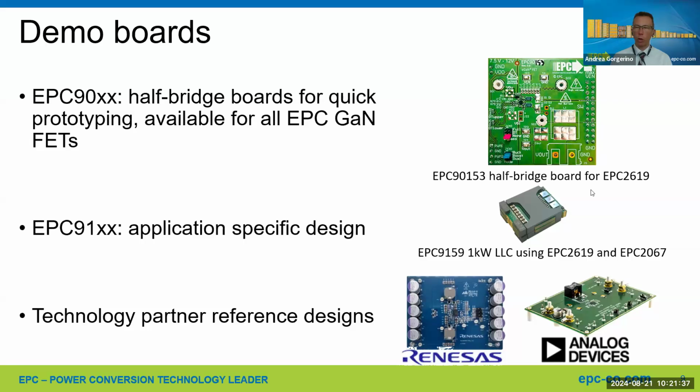The latest generation ones also have some mountings for a heatsink to allow the exploration of different thermal cooling solutions. And this is really the fastest way to validate the calculation that you did in the previous steps, right? It's not a full application, but it allows you to test in a condition that is representative of your final application. And this is really important in my eyes to validate the device selection.